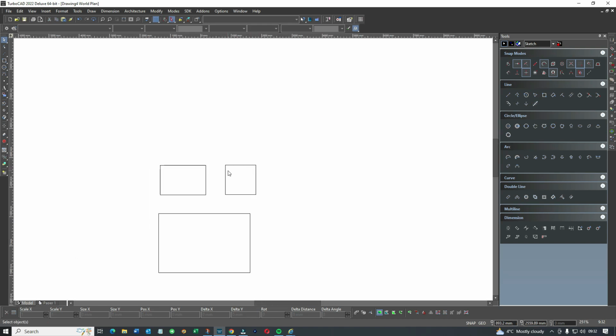If you want to print, obviously what you do is you copy it to paper space, and then you print. And if your paper space isn't set up, or you don't know how to set up paper space, then just check one of my other videos, because I've recently done a video for how to set up the paper space.